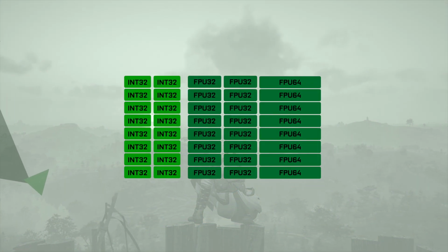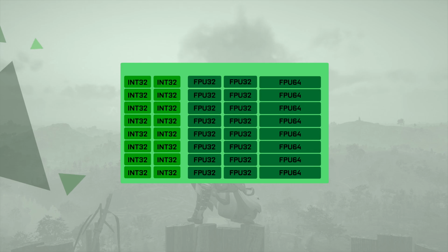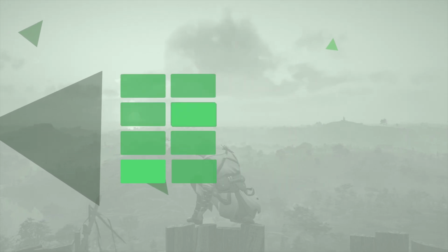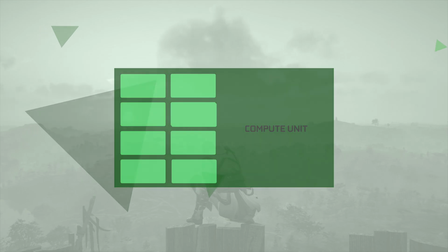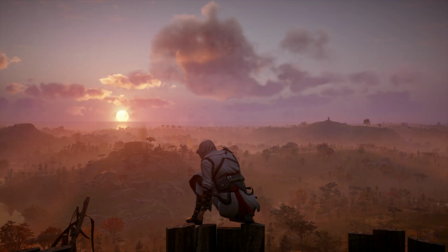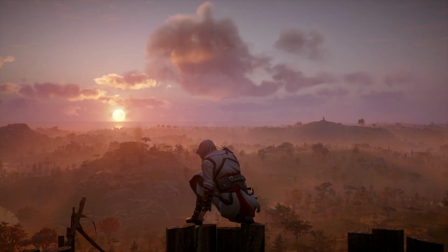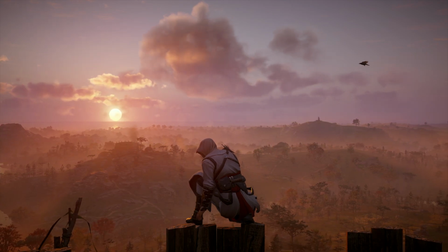The shader processor itself, unlike Nvidia's, operates with 64-bit floating point instructions, and AMD has 64 of them per one compute unit. The main differences between RDNA 1 and 2 are hidden not in logical structures but in the memory subsystems and supported technologies.